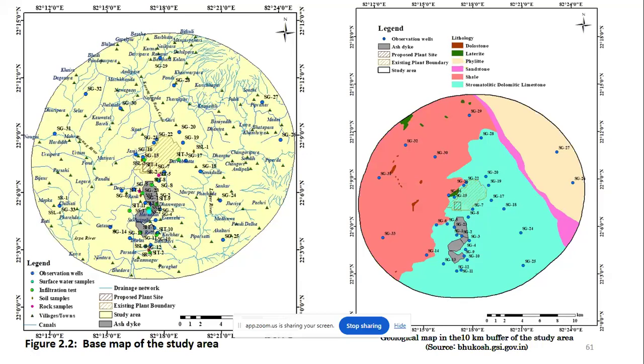And then after that we calculate the probable direction of the groundwater flow. We can measure these things by using various techniques. We measure it generally regularly. So after that we understand the entire geology of the area. What is the stone type, what kind of rocks are there in the particular area, and then it will help us to understand the contamination or the environmental damage contributed by this particular industry.